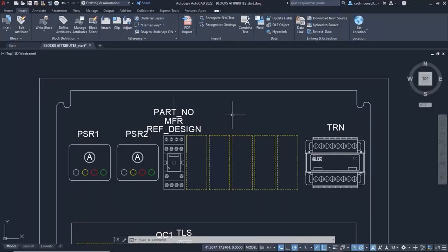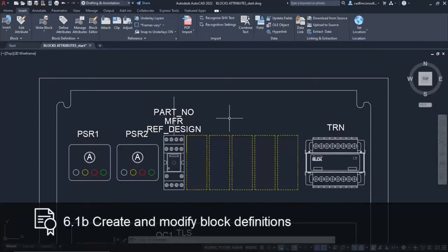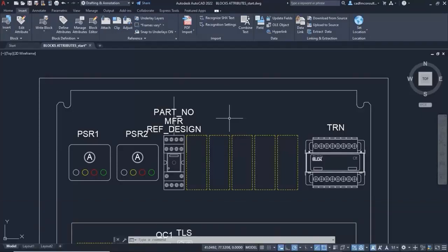It's now time to create our block in our AutoCAD drawing. And it's going to be a global block, so I'm going to write it to an external file which can then be placed on a server or emailed to people. It can also be stored in the cloud, for example. So what I need to do now is go to the block definition panel on the insert tab on the ribbon. And one thing I am going to do is delete the line here. We don't want that forming part of our block. So I'm just going to delete that first, and then it's up to block definition here.